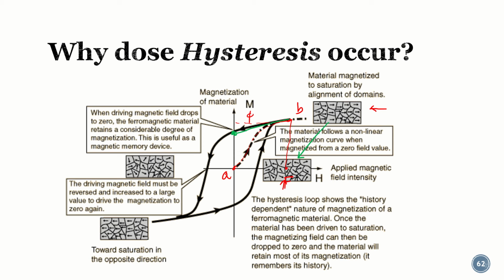Now what is actually happening is that although you have made the magnetomotive force 0, there are still some regions which are aligned, meaning there is some residual flux remaining inside the material. To make that flux 0, we have to restore the random orientation, we have to remove the alignment. So we apply some external negative magnetomotive force so that they become disaligned at this point.